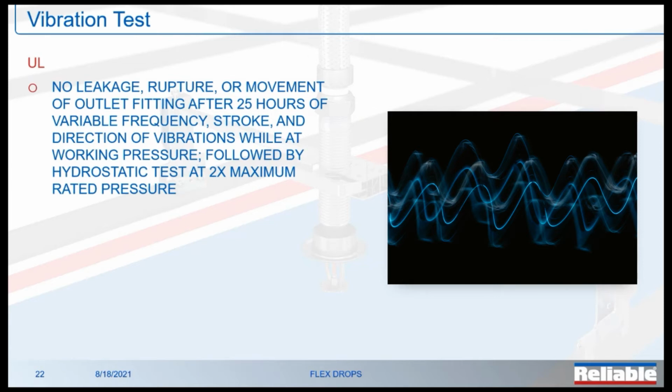Now, they go a little bit further. If anybody's, and I'm sure most people have, right? You have that one bass note in your car where that speaker just seems to sound like it's going to fall apart, right? Everything kind of vibrates and you're like, wow, I got a crappy car. Well, it's actually a natural phenomenon. It's called resonance. And resonance is when the test frequency gets very near to the natural frequency of the assembly, be it your car speaker in your door or the flex head. And you've probably all seen this. There's one spot where everything kind of just goes wonky, and that's resonance.